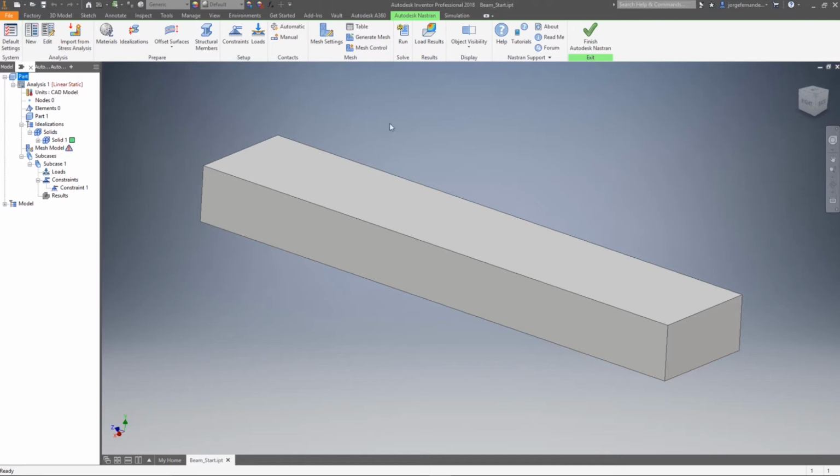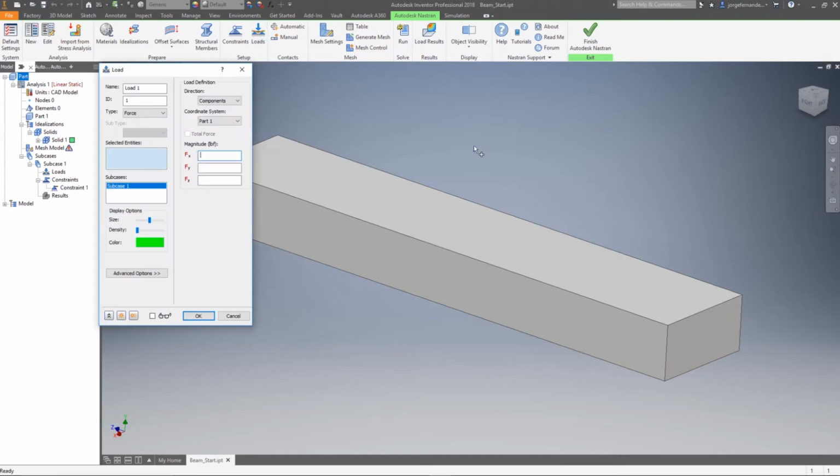So now that we've added the constraints, we'll take a look at the load. And we're going to apply the load, if you remember, on the right-hand side here. And we're going to go negative 1,000 so that it goes down. Notice that you can, over here, tell it the direction according to the component or normal to a surface or to a geometric entity. And you have more than forces. Again, you can do more than linear static, right? This is just an introduction to linear static first.